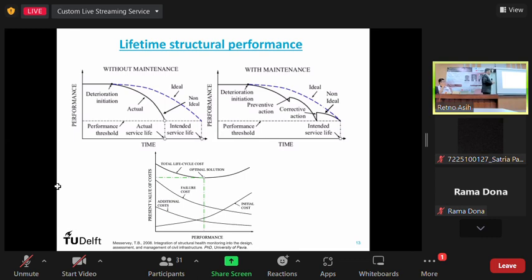Then what happens? You have to shorten your life cycle. You have to replace quicker. And that's the optimistic situation. But there are situations where we have designed for this and it fails at this. Imagine an aircraft that is designed to fly a specific number of cycles, but fails in the middle of the air. Well, we cannot do that. It's costly, it's dangerous. As a result, we always tend to replace them earlier. So we don't want to risk our lives, or have risky, catastrophic failures.